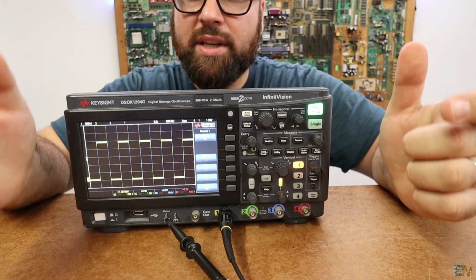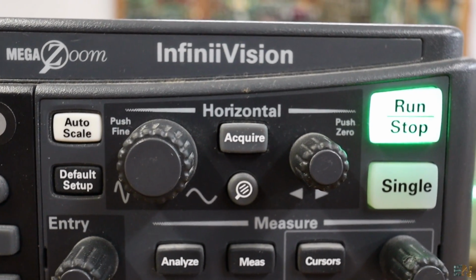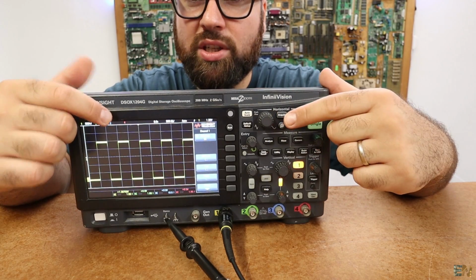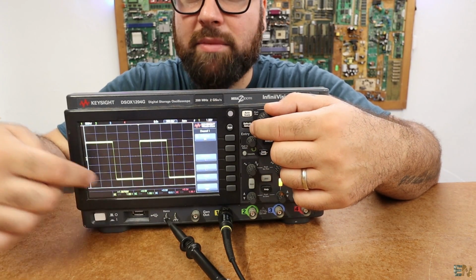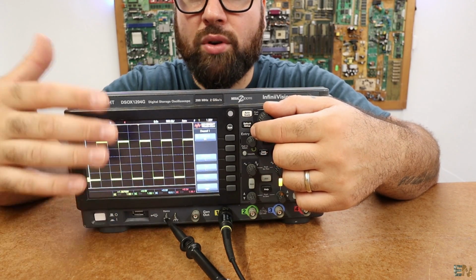Okay, so now we have our signal, but then we have two knobs here on the horizontal line and two more knobs here for the vertical line. These two are for controlling the scale and position of the horizontal line, which is the time. So as you can see with the big one, I can zoom in and zoom out, basically changing the time division so we can know the time of the signal. And this is for all the channels.